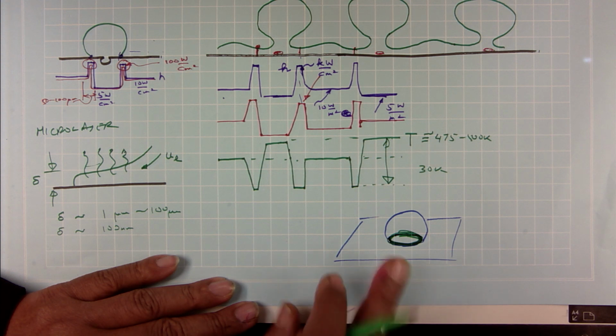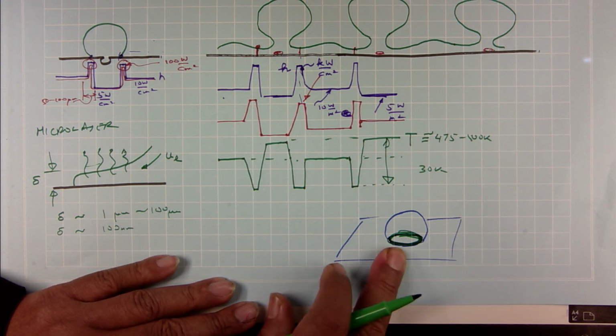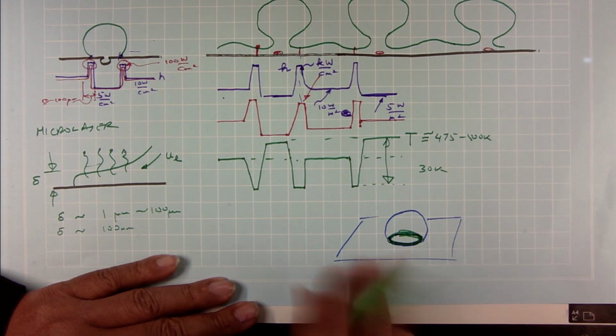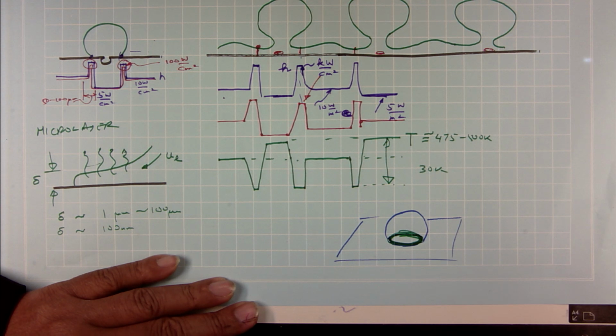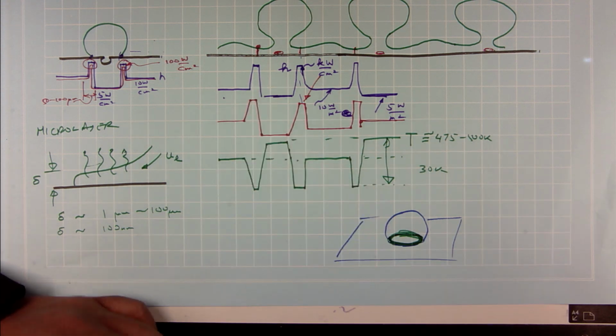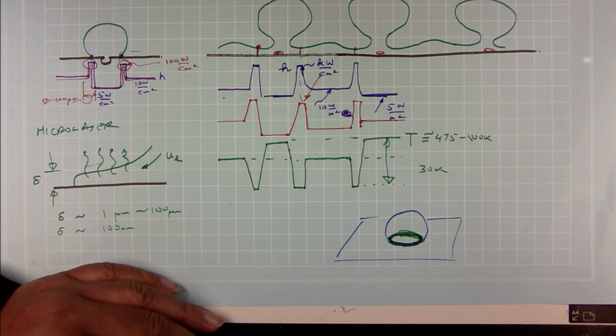Okay, so, if I want to enhance boiling, all I have to do is either increase the contact line or increase the number of bubbles, right. So, the more the number of bubbles, more the contact point, more the delta function in the heat transfer, because effectively this is a delta function, isn't it. Wherever there is a cold spot, there is a high value of heat transfer, and wherever there is no cold spot, it goes to like 5 or 10 versus 1000. So, effectively it is a delta function.